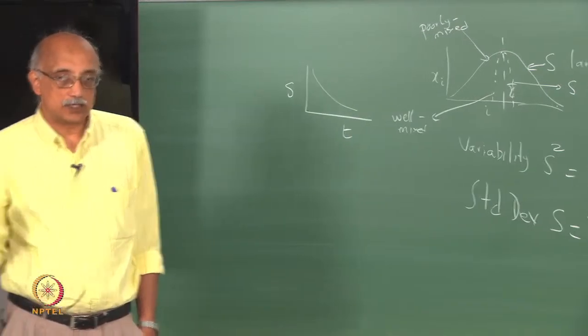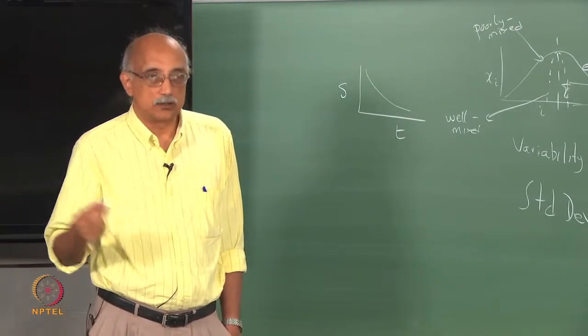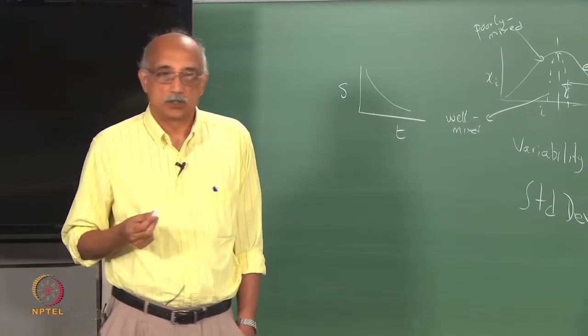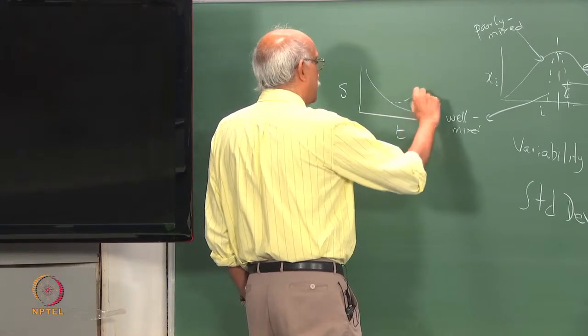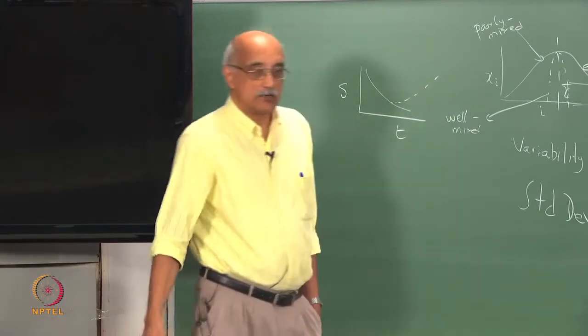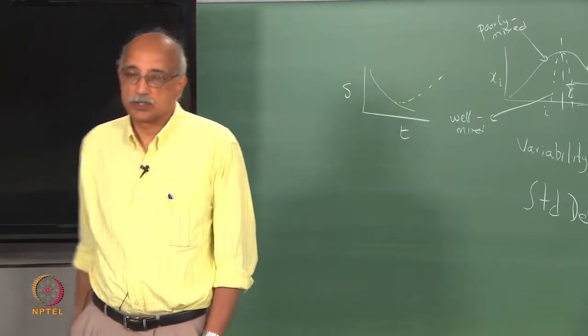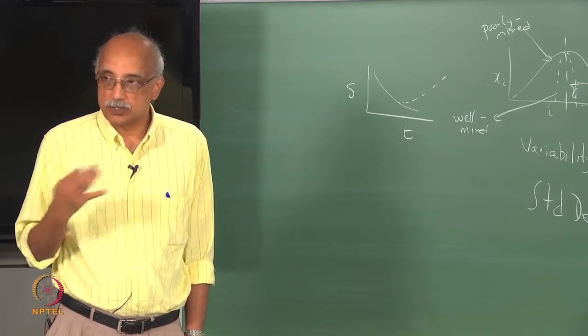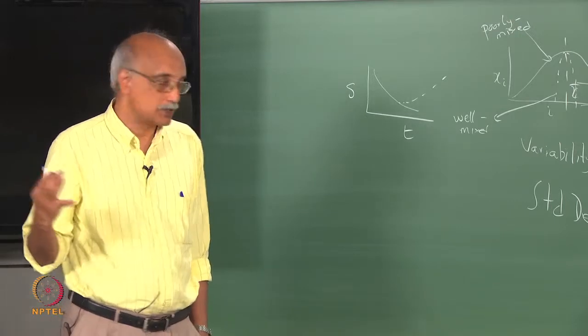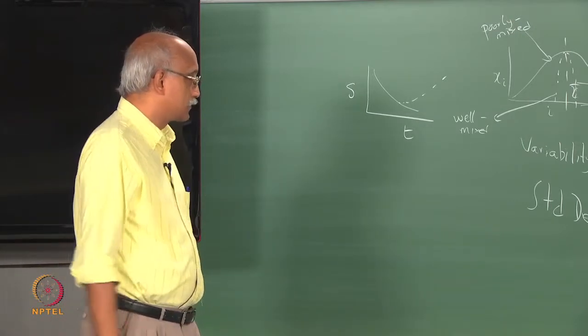This is in a mixer which is working well, functioning effectively. But as I said, there could be cases where you go like this and then the standard deviation starts to increase again. So, you need to keep your eye on the behavior of the material that you are trying to blend and really understand its mixing characteristics.